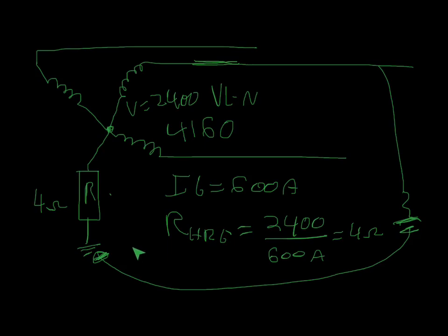And if you do find that it's a short circuit or that the path is closed, you're going to want to check your loads and make sure that nothing is connected to ground. And if you're working on a main system, a lot of times these feeders run a distance, and they may be tied into another system or something else that is grounded. And if it should be grounded, that's fine. If it shouldn't, you need to verify that that fault current isn't going to run back on your grounding system and defeat the purpose of this high resistance ground.